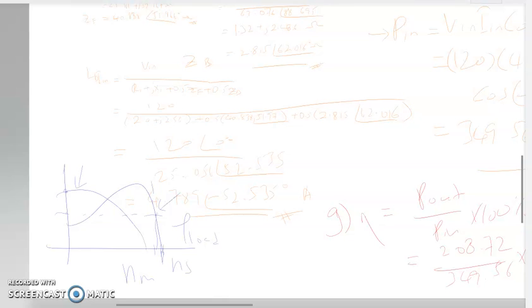And if you start the motor without the starting circuit, you are not able to push the load or the shaft, because the load is already connected with this full load torque here.